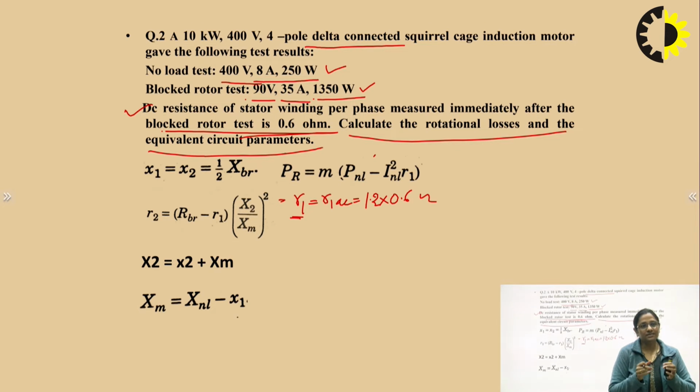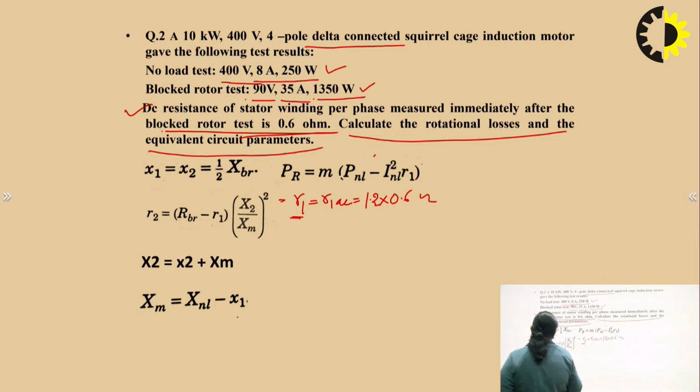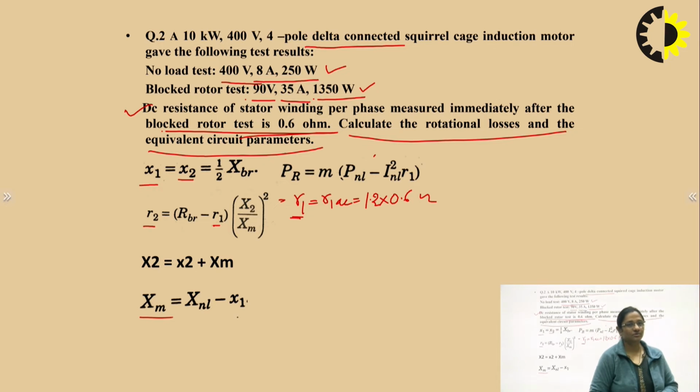And you know that this circuit is nothing but a series parallel RL circuit only, right? So, the analysis of the machine becomes quite easy for any condition, for any type of loading, if we have the equivalent circuit of the machine. The various parameters of the equivalent circuit are resistance R1, resistance R2, reactance X1, reactance X2 and the reactance XM. XM is the magnetizing reactance of the machine.